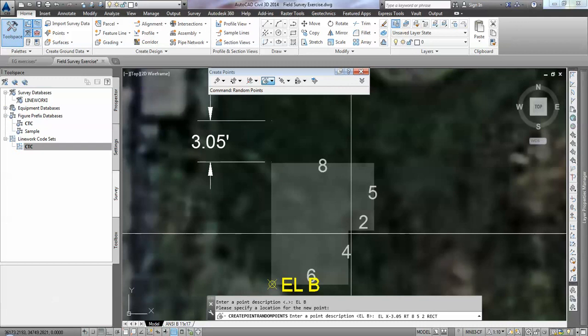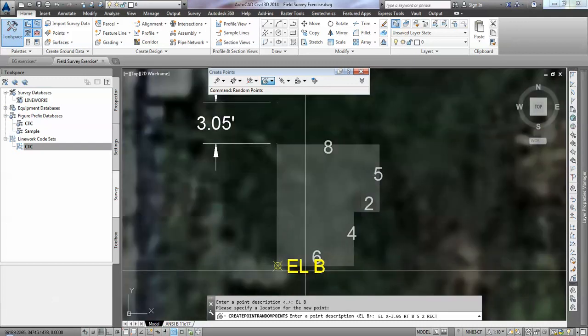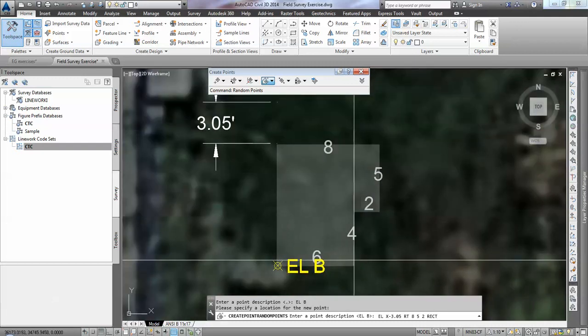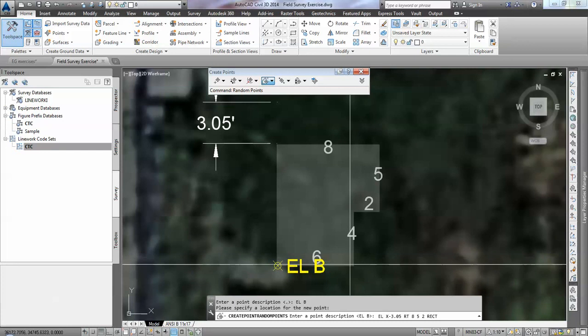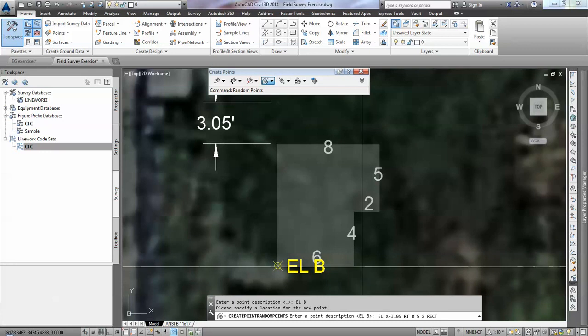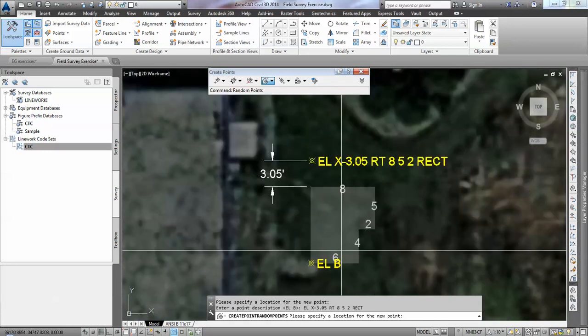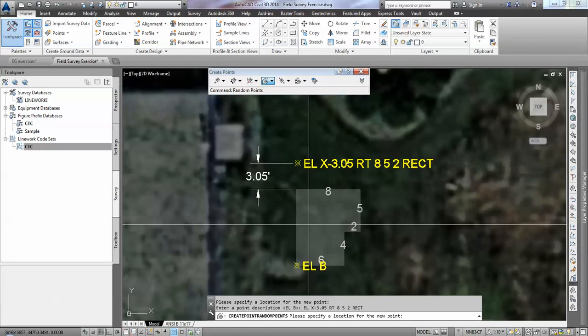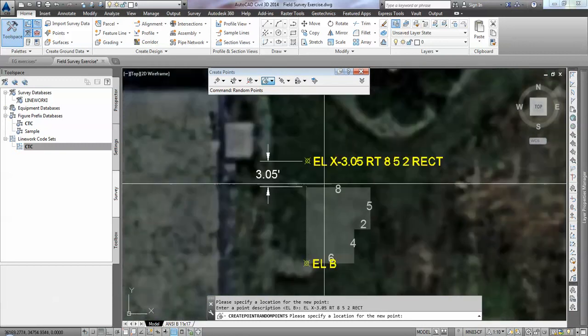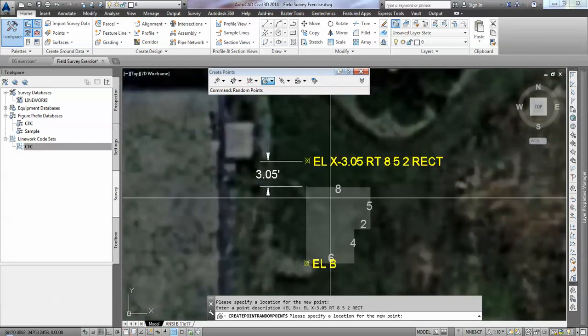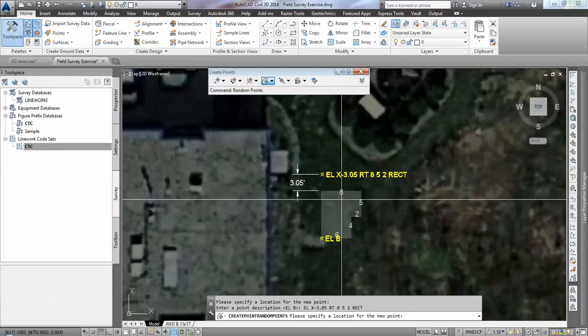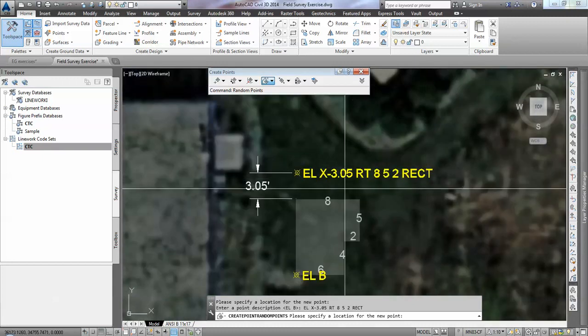What a rectangle will do is find the last corner of any figure it's shooting and project two perpendicular lines to find that point, and then close the survey figure. Okay, so a complicated shape I can shoot with 2 shots. This kind of strategy works great for shooting small little indentations along a building outline, or small little sheds where you don't need to shoot the back corner, for example. There's a lot of different ways to use the RT, the rectangle, as well as the extend command.